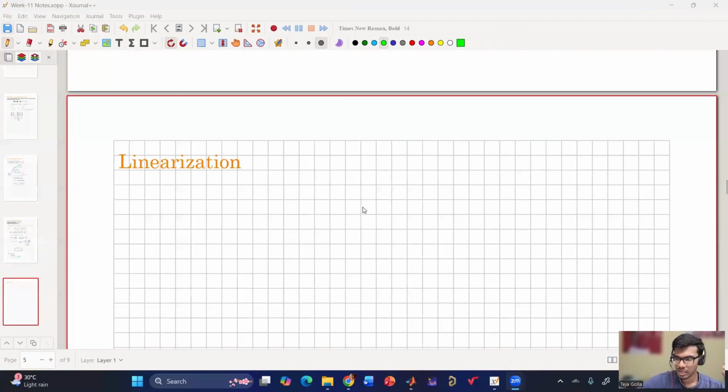Till now, we have considered the state space model to be linear, or a linear combination of the x1, x2, x3, x4 states. But what happens if the system is not linear? Say I have x1 dot. Previously, it was some scalar product of the states and addition of that.